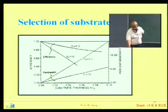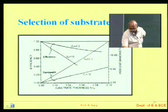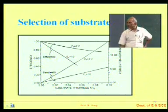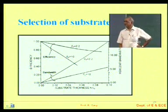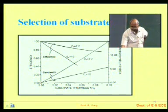You can see that for epsilon r 2.2, I think this is the bandwidth. Bandwidth is almost linearly increasing with the substrate thickness, going up to 15% bandwidth when h by lambda 0 is around 1 by 10. When thickness is lambda by 10, it makes something like 15%.